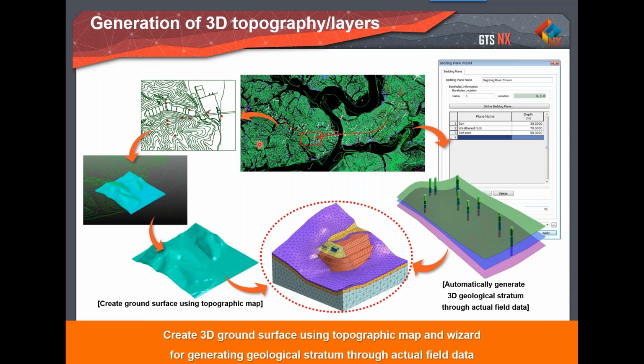And we have an important tool called terrain geometry maker. Let's say you're dealing with a hilly terrain like this kind of scenario, and you want to model a particular area. In order to model this area, you need various kinds of inputs, like contour data, or you might have the lidar survey data. You can simply input all such data into this software. In the case of contours, you can simply import the contour data, and then the software will create the surface for you. And this surface creation is done by Terrain Geometry Maker.